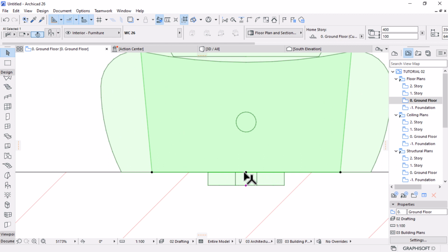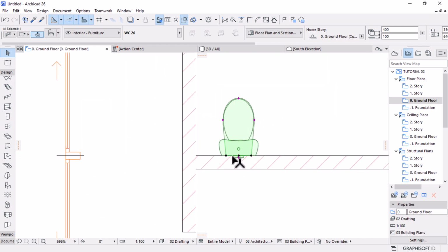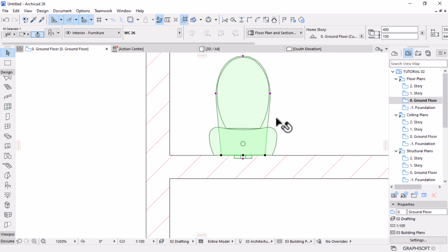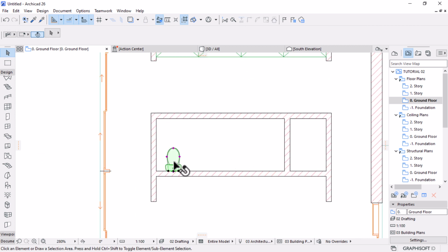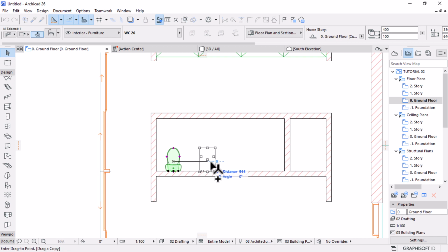I'd like to position it by the hotspot because this is just the inlet or the connection point of the sewage when you're using MEP tools. This is where you connect this MEP equipment to create your plumbing system or sewage system. All right, and then I can Control Shift D to move a copy here.